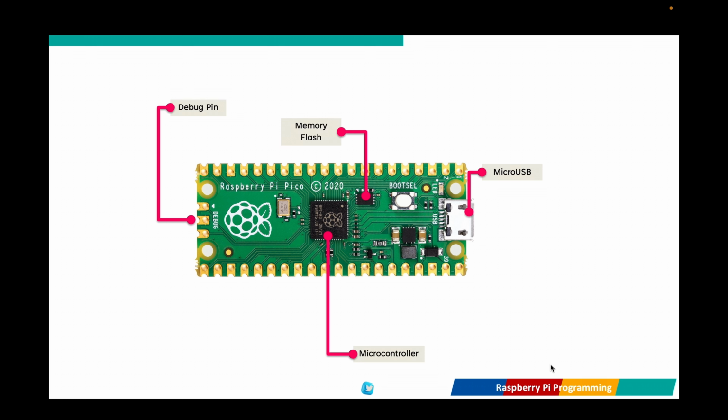The Raspberry Pi Pico includes a USB 1.1 port which serves two functions. Programming interface. This is where the Pico can be programmed via USB by dragging and dropping UF2 files. Or USB device or host mode. It acts as a USB device like keyboard or mouse or even a basic host in some applications.